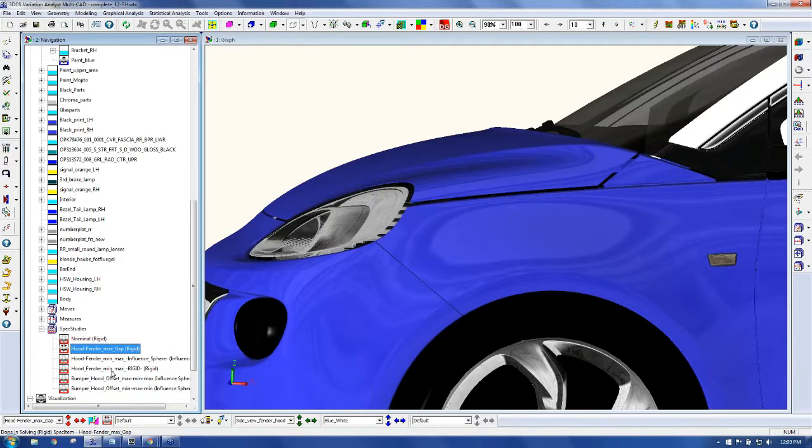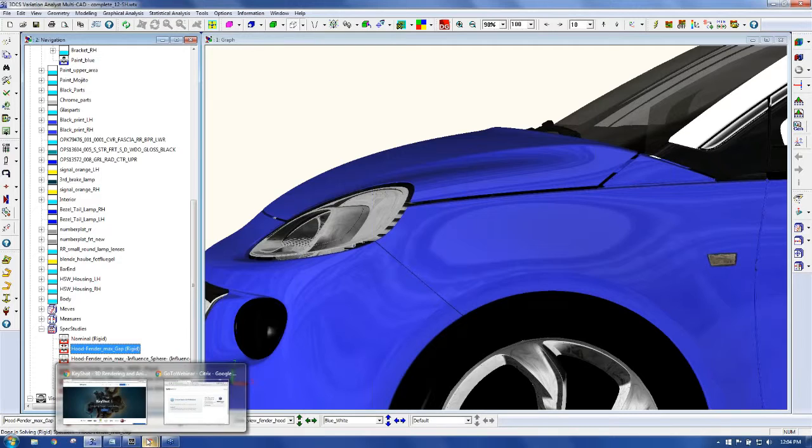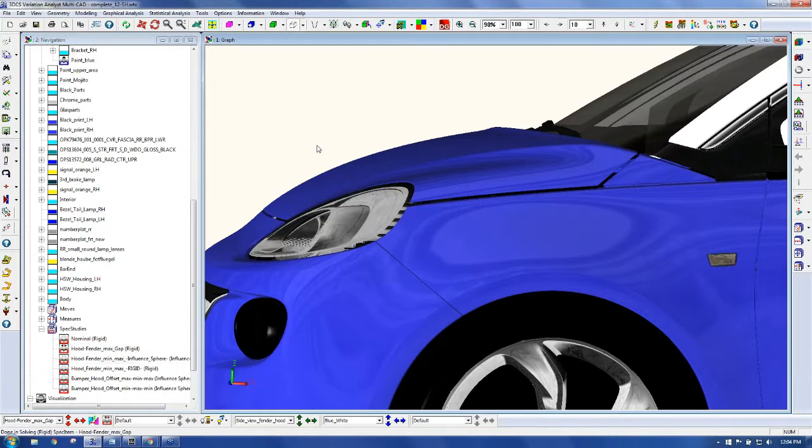So now, so if I wanted to make my own, you'd probably need like a specialist tool. You would need a special camera to be able to shoot a 360-degree image, but it can be done. Definitely can be done. You can also just set up a backplate image. You can bring in your geometry and then set an image as your background. The thing to note about that is you're going to have to match your camera angle to the camera angle of your backplate.